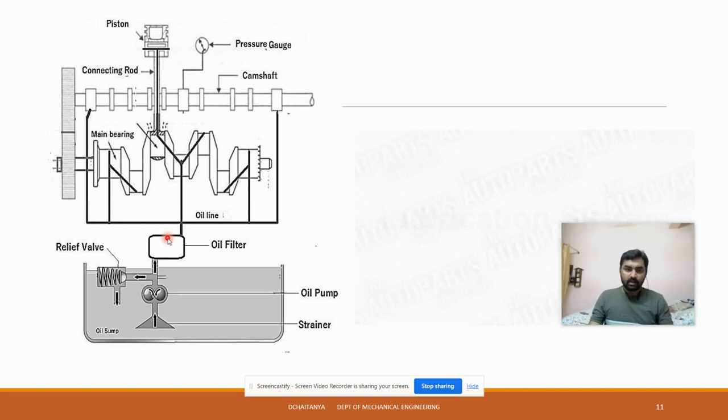The black channel itself does the pumping for the camshafts. Here there is a crank, bearing positions, gudgeon pin. You can see here the piston rings. This is called the oil line system, which can be seen as minor thickness passages inside an engine. During manufacturing only, they keep those lines. Channels, not lines, those channels.